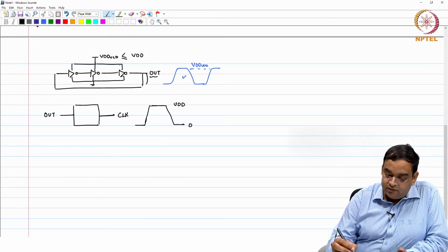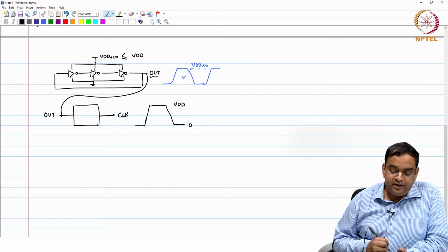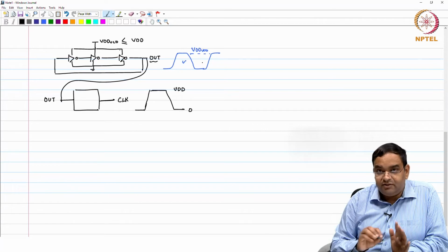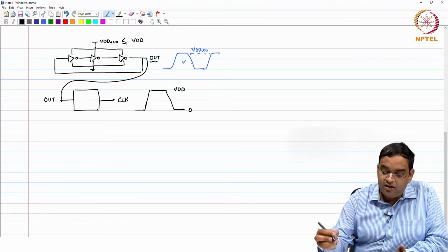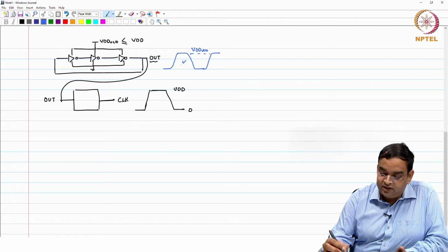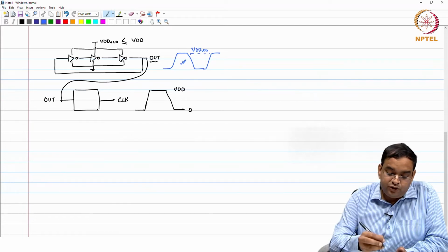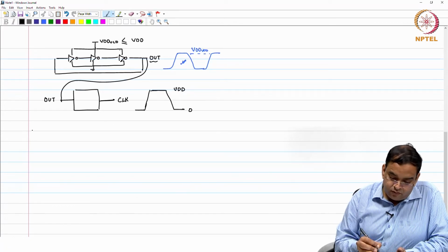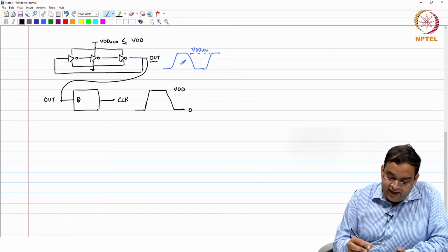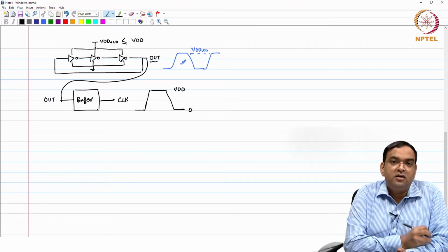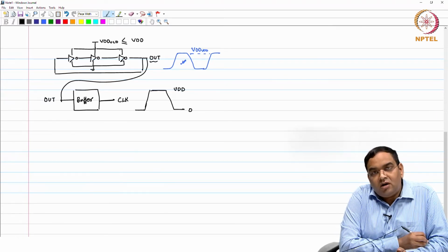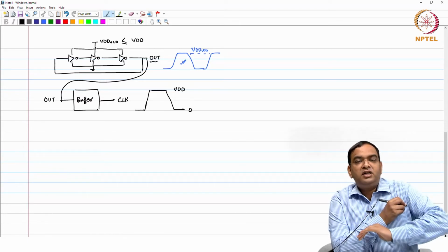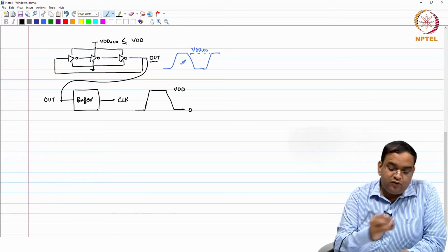Okay. So, this out signal is this, right. We do not want to change the frequency. Whatever signal you have here, the signal you had previously, as shown here, gets restored to 0 to VDD, and nothing else do we want to change. So, this block should act as a buffer for the clock, where the clock frequency is retained, and the only thing is the swing is amplified to full scale.